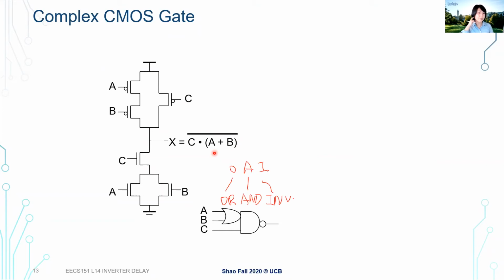So this is basically how we talk about going from truth table to Boolean algebra, and also you can map to a circuit. Of course, there are different ways to map a circuit, but when we design a CMOS gate, this is basically how we either turn a CMOS gate into a Boolean equation, or turn it into a truth table, or the other way around, start from the truth table, get to the Boolean equation, and then design CMOS for it.